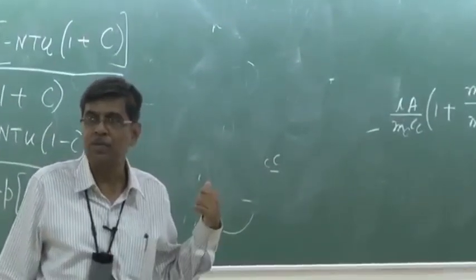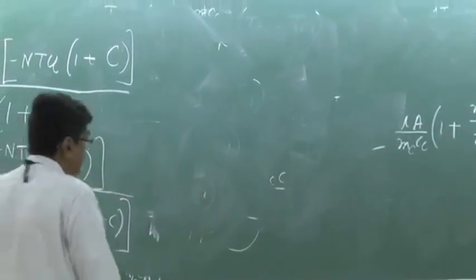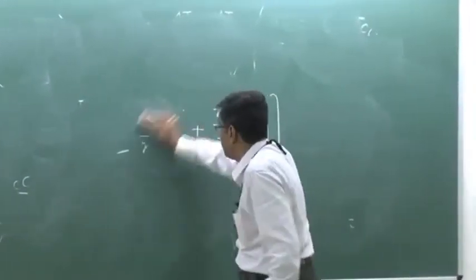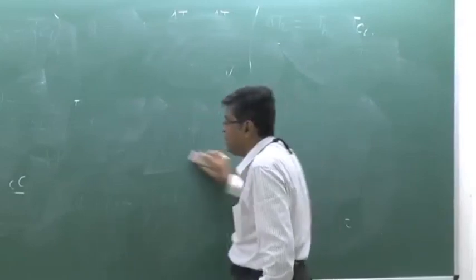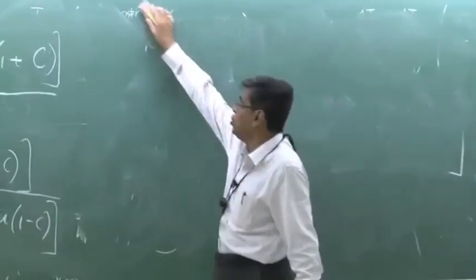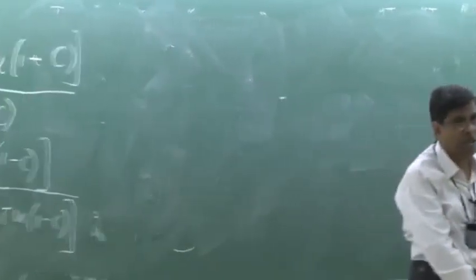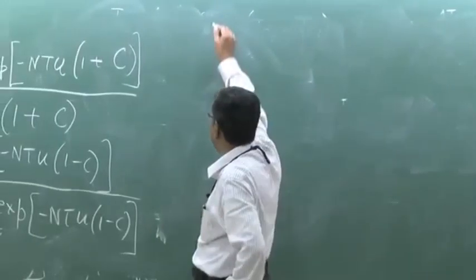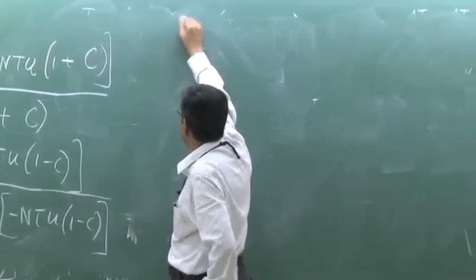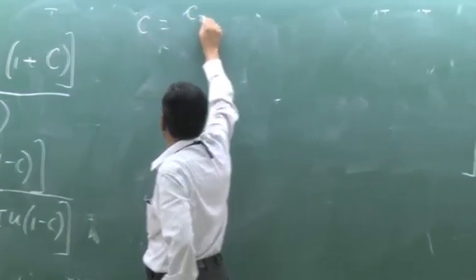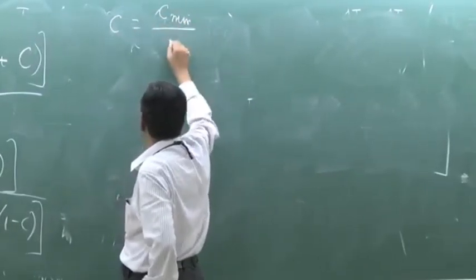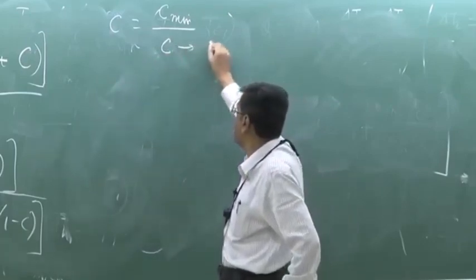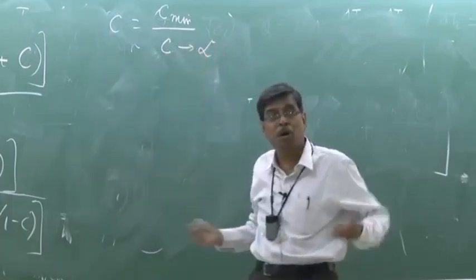But now mathematically you see that for a condensation and boiling problem, the specific heat of one of the fluids tends to infinity, as I showed you earlier in the figure. That means this higher C tends to infinity, because it will always be the higher one.